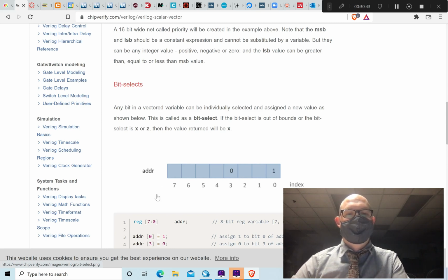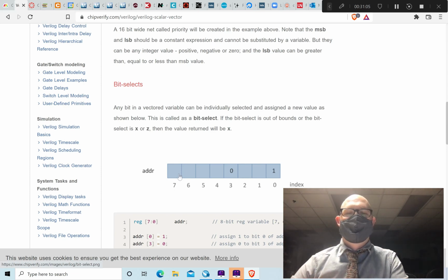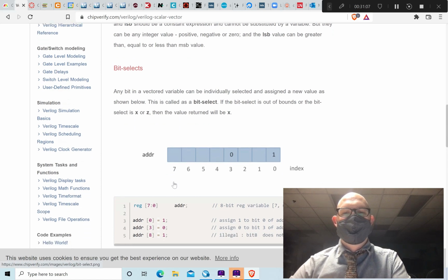So from left to right, when you do it 7:0, which is the standard way, that talks about endianness basically, and this makes it, when it's on the right, that's little endian, because it starts, no, it's big endian. I can't remember. I'm not going to look up endianness. Go look it up. It's one or the other, but it changes the endianness of the vector. So when it's 7:0, the thing to remember is that the biggest number is farthest left, the littlest number is farthest right.